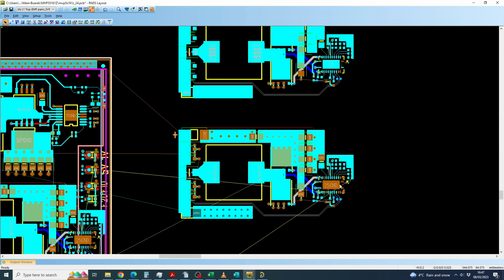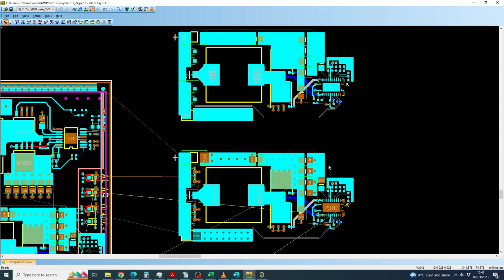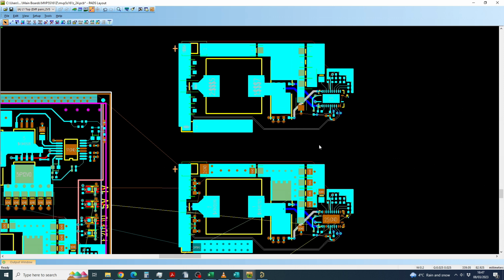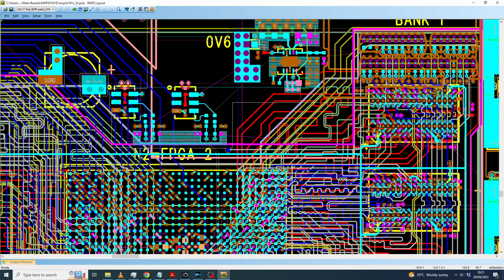They were all previously converted to stitching vias. I don't know how to preserve those when I copy circuitry in the PCB layout. It'll probably take me 10 or 15 minutes to go back and fix all the things that are missing, but it's still worthwhile. Okay, so to achieve closure on this refresher video, I thought we would just look at the